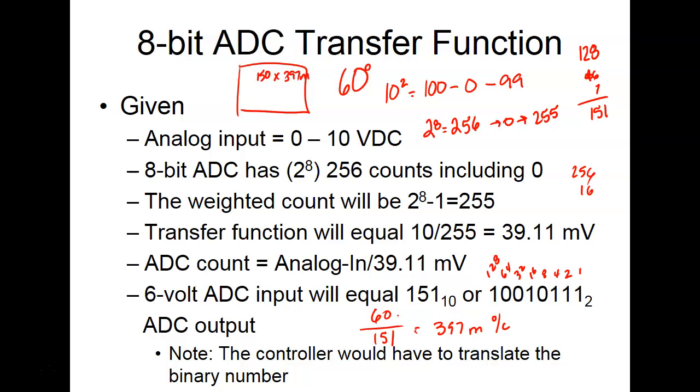We're going to run into a lot of analog to digital converters, and on a programmable logic controller you'll have to figure out the transfer function, because you'll have to do the math to make the PLC display the actual quantity, not the binary number that it represents. The more bits you have, the more accurate it is. The MicroLogix 1100 we have has a 10-bit A/D converter. That's 2 raised to the 10, which is 1024, and then we subtract 1, so we could split that up into 1023 different steps.